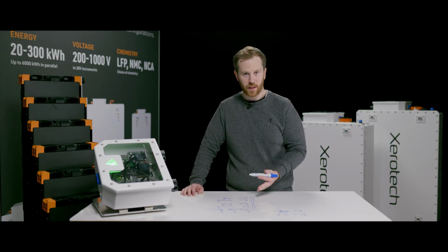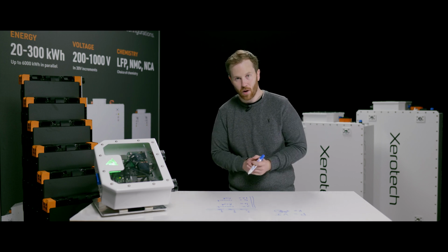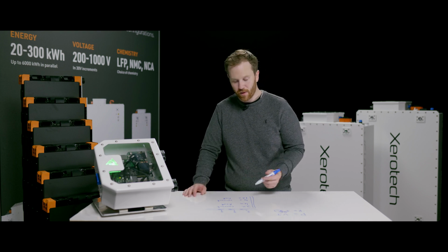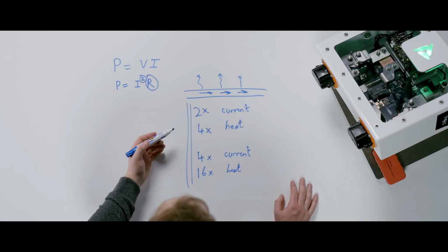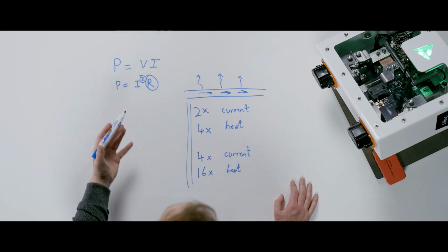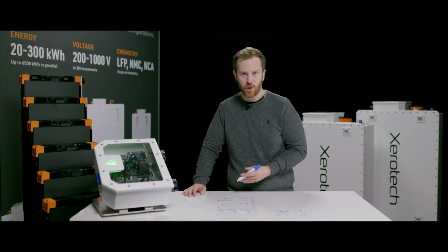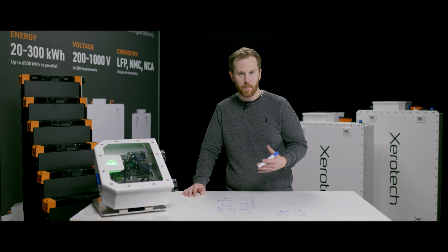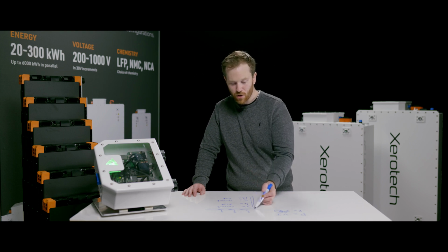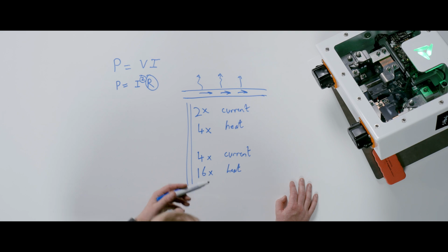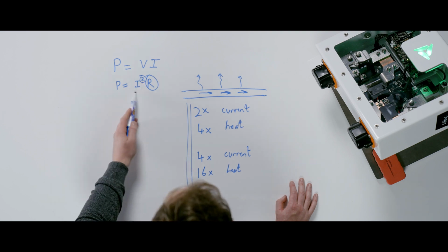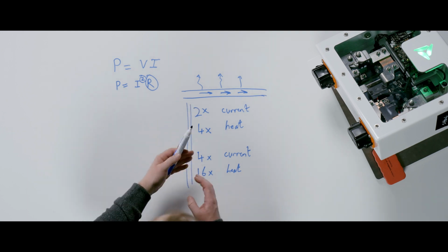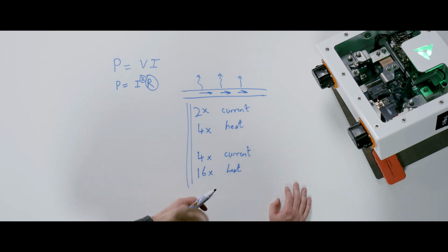Keeping currents down does a lot of things. It makes your conductors smaller, and it makes the amount of heat generation a lot lower. So modern electronics, by being at higher voltage, have fewer losses, fewer failures, and fewer issues, because they're not having to deal with heat rejection. In fact, that's why you have to liquid cool a battery and modern power electronics: you're largely trying to eliminate these efficiency losses. Keeping the currents down is really important, and the way that's achieved is using high voltage, insulated wires to minimize losses and maximize your power output.